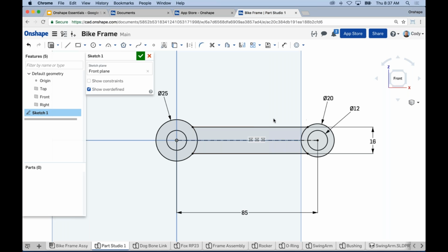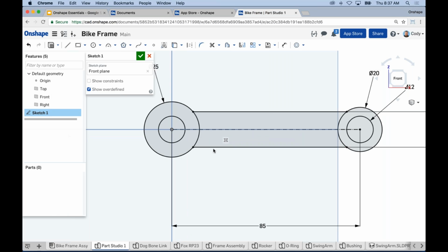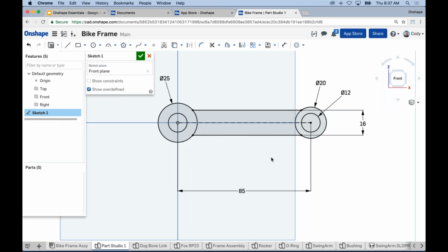So that's one big thing. Again, the other thing to keep in mind, if I had this line and another line right on top of it, it's not going to affect my feature. I can still create a feature just fine. So no, we don't have sketch analysis, but I think in the two examples you gave, it shouldn't hurt you, right? You can see the shaded profile, and overlapping lines aren't a huge issue.